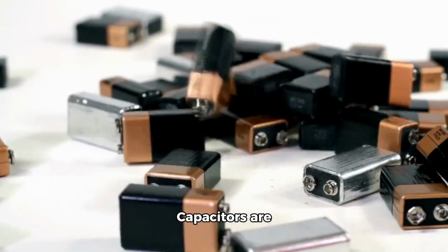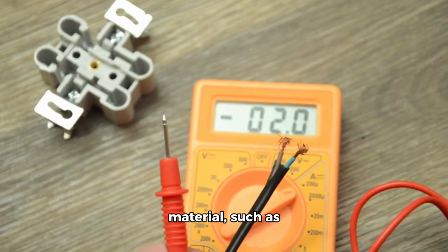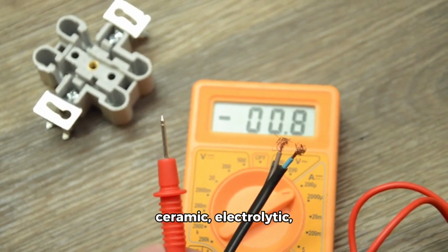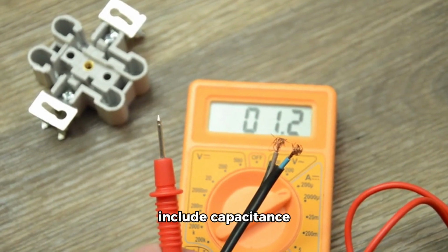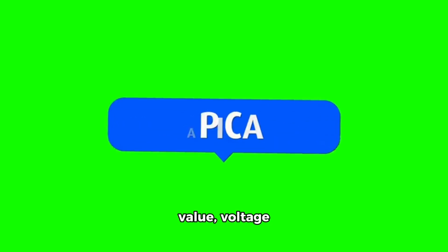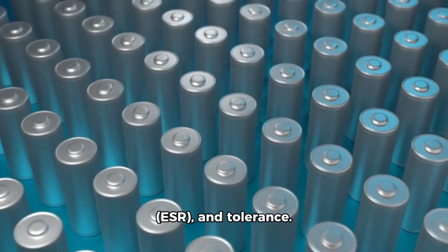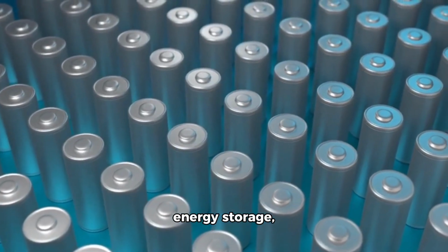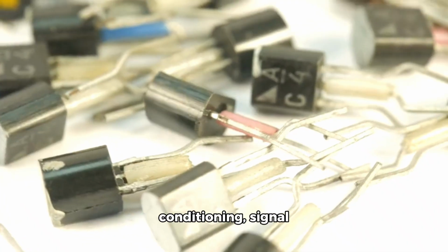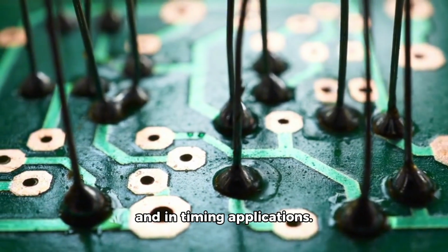Characteristics: capacitors are classified based on their dielectric materials such as ceramic, electrolytic, tantalum, and film capacitors. Key parameters include capacitance value, voltage rating, equivalent series resistance (ESR), and tolerance. Applications: capacitors are used for energy storage, filtering, power conditioning, signal coupling and decoupling, and in timing applications.